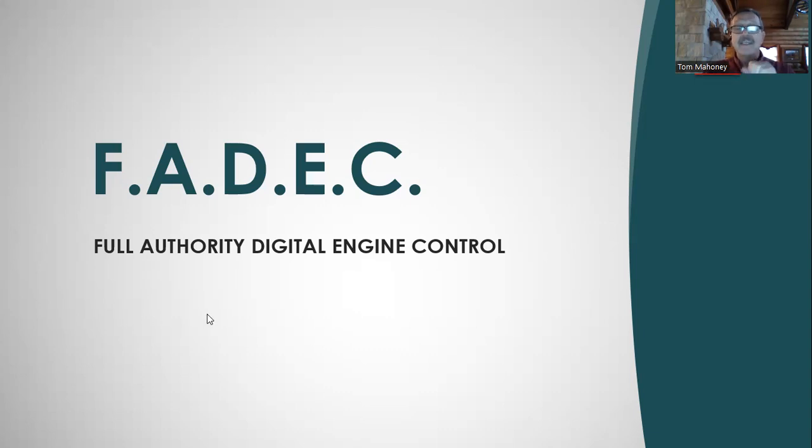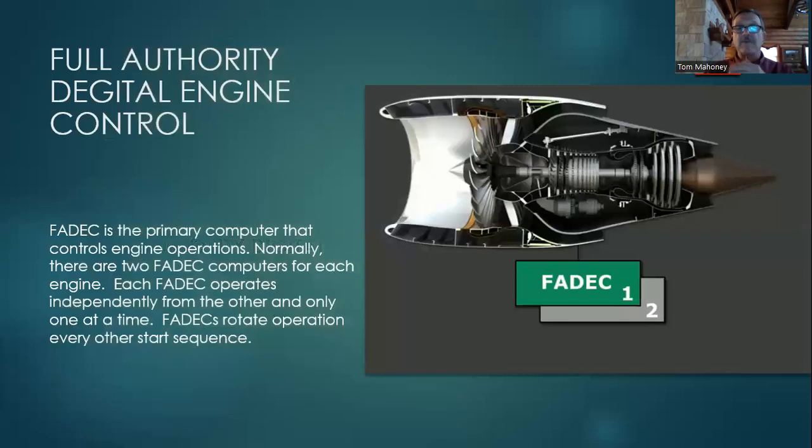And it tells the engine how much fuel it should be taking in, how much air it should be taking in, what the RPM should be, etc. So it's full authority digital engine control. The FADEC is the primary computer that controls the engine operations. Normally, there are two FADEC computers for each engine. Each FADEC operates independently from the other and only one at a time. It only takes one FADEC to operate the engine.